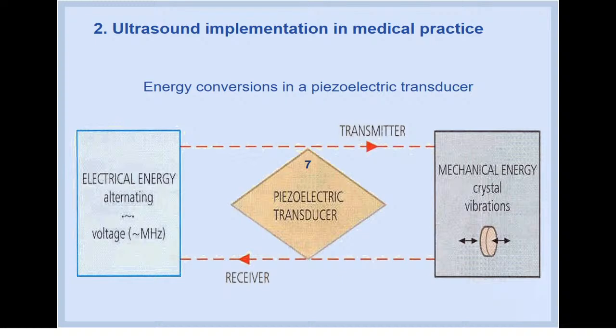If pressure is applied to the surface of appropriately cut plates or discs of certain monocrystals, for example quartz, electric charges are generated. This is the piezoelectric effect. The effect is reversible: if electrodes are placed on the crystal plate and a potential difference is applied to the electrodes, the plate will be deformed by the electric field. This is the inverse piezoelectric effect.